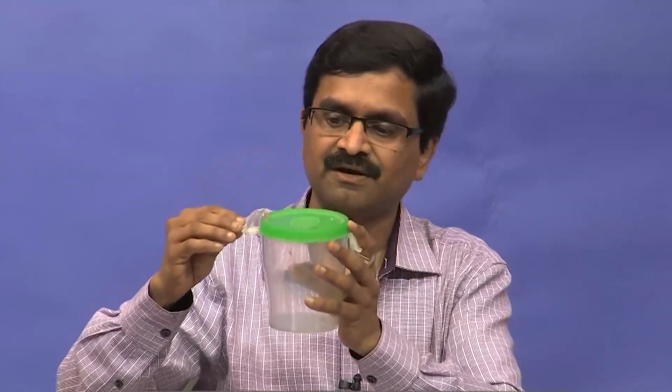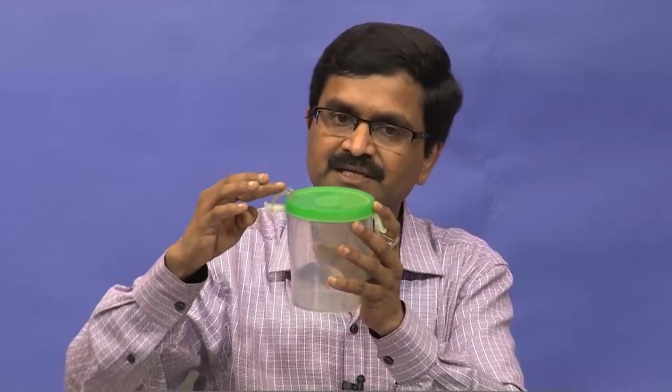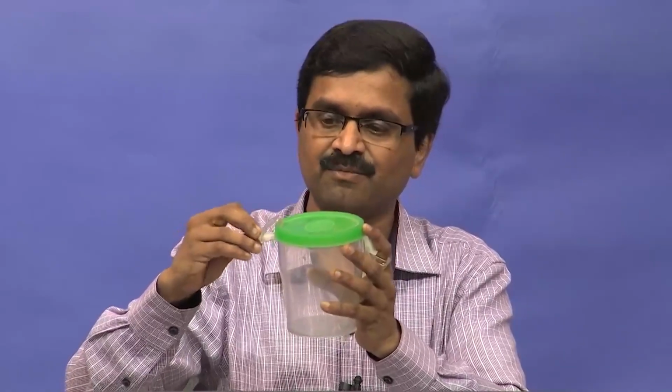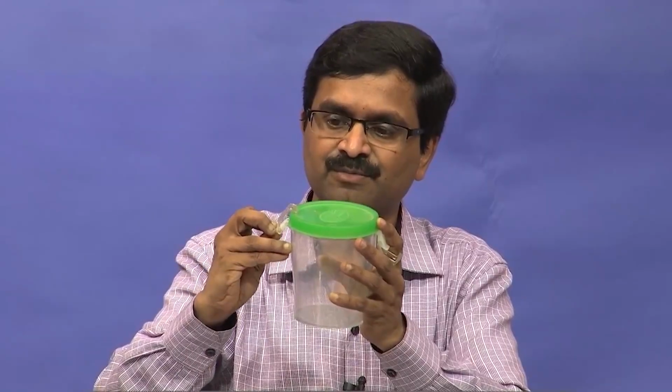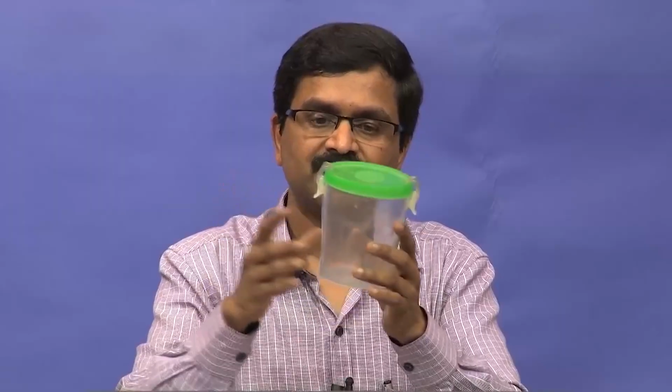That is, it cannot move anymore like a rigid body, but this particular thing can actually flex, that is, elastically deform, so that it deforms and allows more rotation, and when I push further, it actually becomes bistable and it snaps. If I do it fast, you can hear the sound as well. So this is a mechanism that has a smooth transition from a rigid body serial chain to a compliant mechanism.